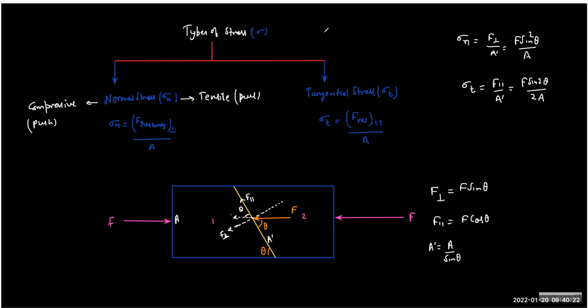So carbon, by virtue of its size, easily fits the interstitial gap of the iron crystal, thereby reducing the movement and hence the elasticity, but it adds rigidity. So it becomes more rigid but poorly elastic.